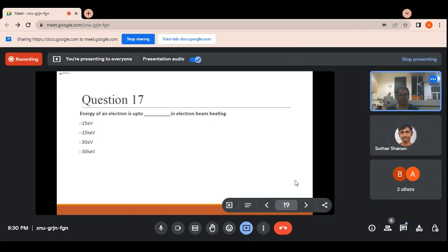Okay. And what about the bright field mask and the dark field mask? So, bright field mask. In a bright field mask, when we want to create structures like interdigitated electrodes, right, then we use the bright field mask, like creating an island above the surface of the substrate. And when we want to create a hole, we go for a dark field mask, like removing a certain portion.